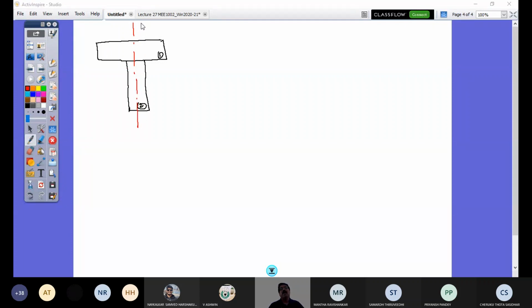So this axis will be my YC axis. What is my XC axis? How do I get it? For that I should have my reference. So for the reference, I take this point. So from this base, where is my y bar located? That's my XC axis. So I will have my centroidal axis, or that is my neutral axis of the section, right? So how do I get that? For that, the first moment principle you have to use. So I have now in this case x bar is 0. That is why I have this YC. X bar is 0, I write, by symmetry.